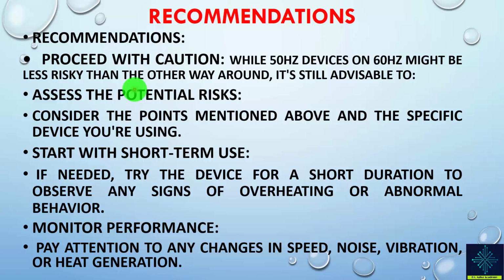I mean, it's more risky to bring some machine from the USA, designed to operate on a 60 Hz system, and operate it on a 50 Hz system, but the opposite is less risky. You can, with less risk, take 50 Hz devices and operate them in the US. I want to remind you that in the US, in some places, you might have a dual system, 50 and 60.